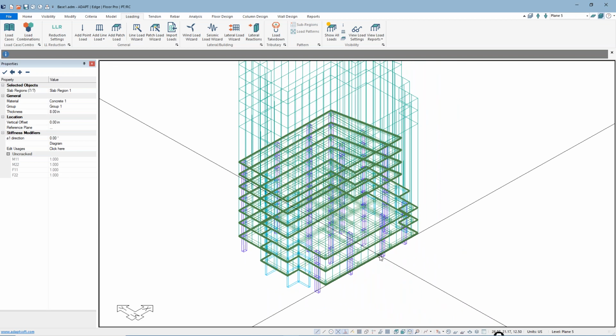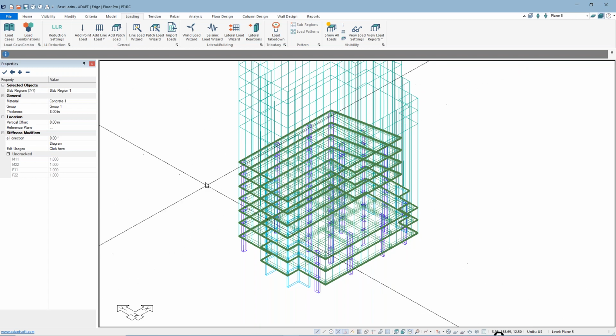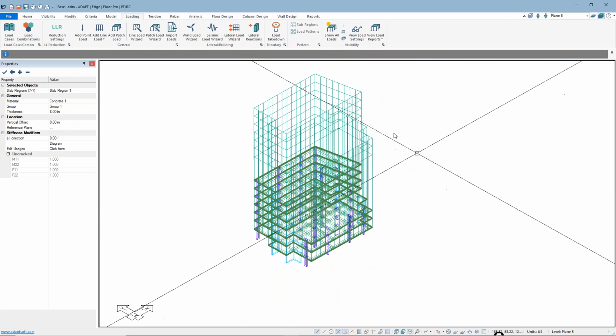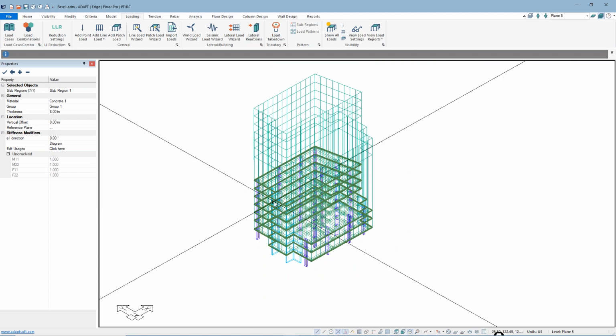In this case, we have beams. We may want the slab and the beam to both participate laterally to resist the lateral forces. So we're going to leave the diaphragms alone. We're going to just assume the semi-rigid behavior of those diaphragms. But I wanted to mention that in case anyone wants to try to manipulate the stiffness out-of-plane or in-plane for those diaphragms, and we'll come back to usage case for that purpose. So we have gravity loads on the structure.